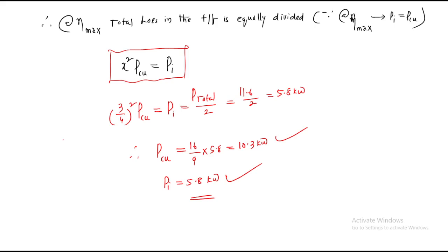So we have to get percentage resistance, which is equal to I2 R02 by E2 into 100, which is equal to I2 square R02 by E2 I2, multiplying I2 by I2.